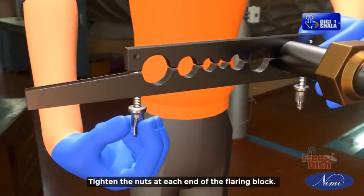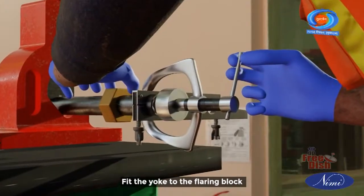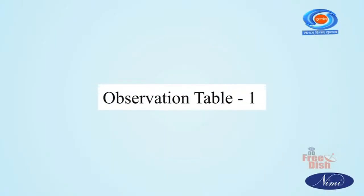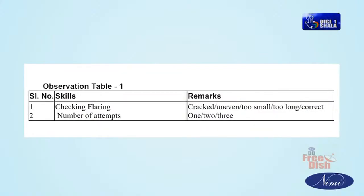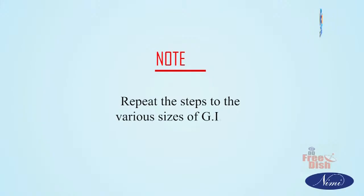Tighten the nuts at each end of the flaring block. Fit the yoke to the flaring block. Note: repeat the steps for the various sizes of GI pipe.